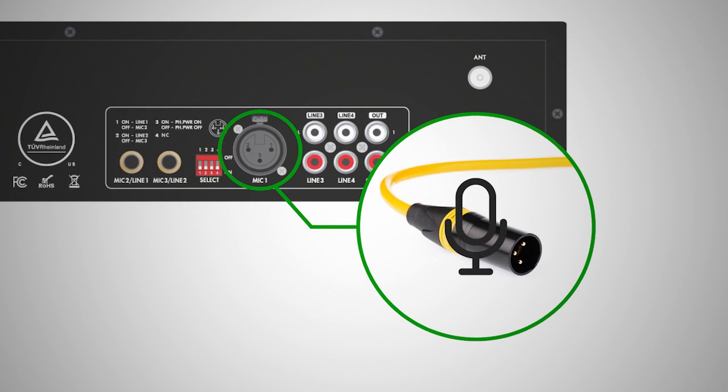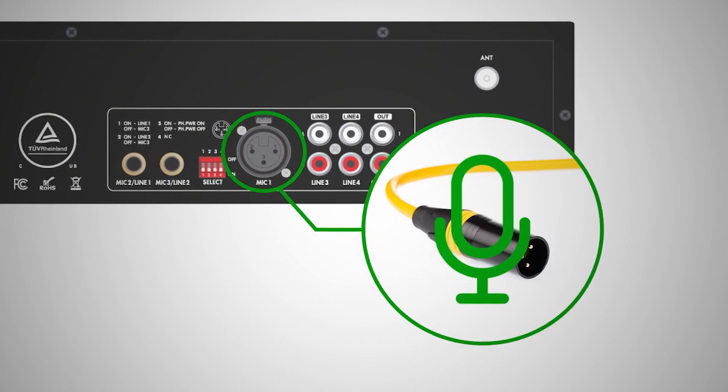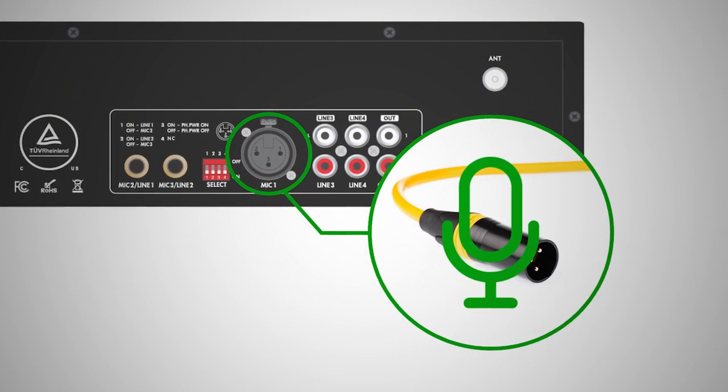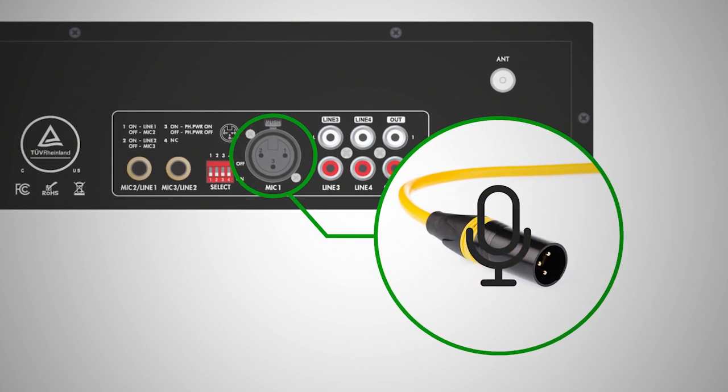which is basically a 2-conductor with a ground, or what they call a drain wire. It's powered by the mixer amplifier, which is called phantom power. So again, these are things that home audio receivers don't have. This is specific to commercial audio amplifiers and mixers. And then when it comes to wiring the speakers, again, 1 2-conductor. So we're not having to run multiple sets of large conductor speaker wire. We can do 30 speakers off of an 18 gauge 2-conductor, and then we just have to do some math.